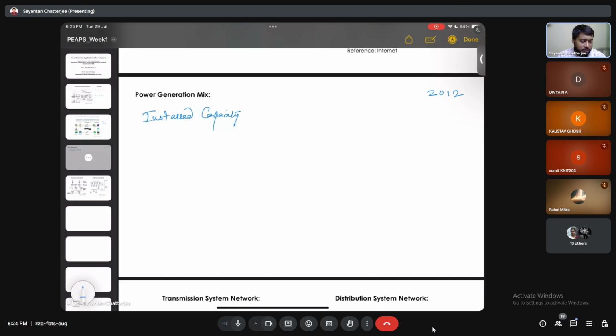It was 29th or 30th July 2012, I guess, 30th July. It was the blackout day. Initially in 2012, from 2013, the entire Indian grid became one grid, one nation, one frequency. But up to 2013, I guess, before November or October, four of the grids, east, west, north, and northeastern, were connected together, right? And the southern grid was isolated, connected by a 500 kV DC link.